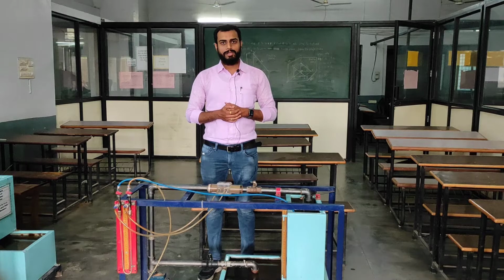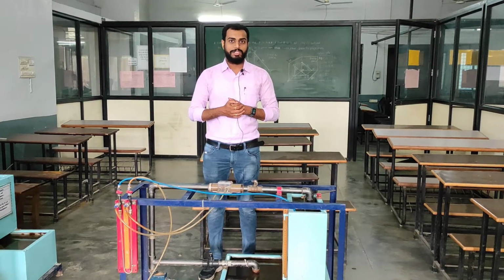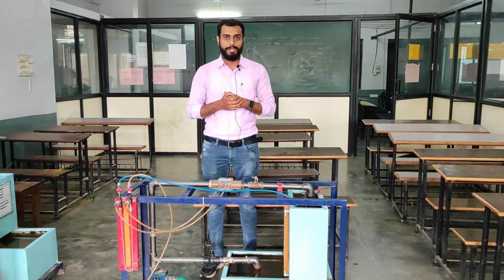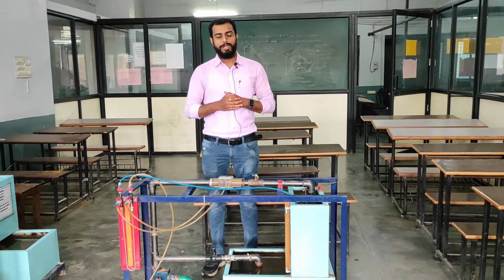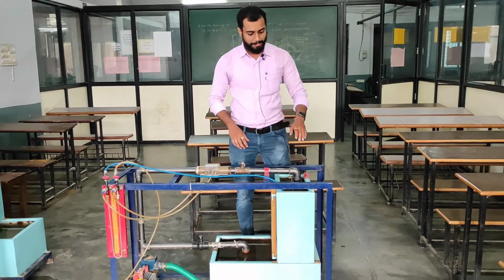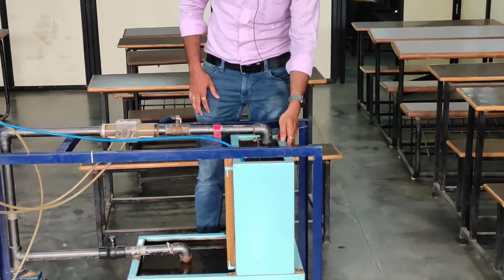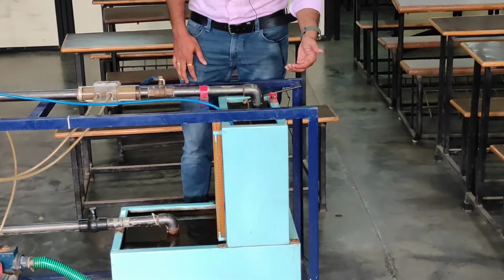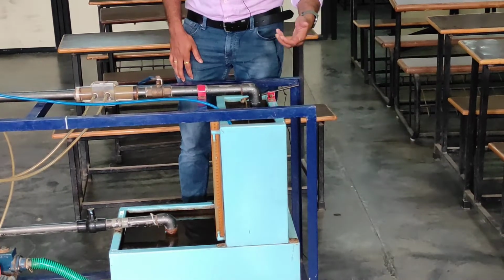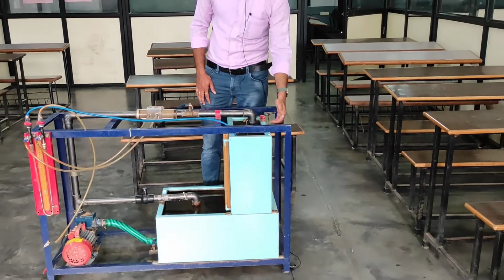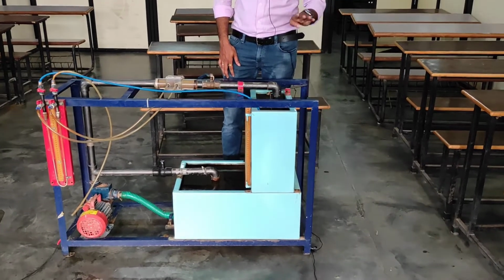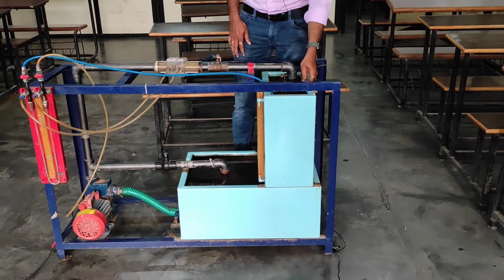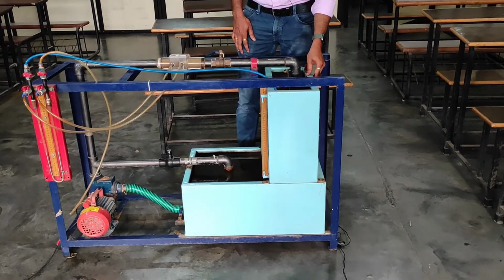Now to find out the CD, that is coefficient of discharge for this Orifice meter, the simple equation is CD is equal to Q actual by Q theoretical. Now first is Q actual. Q actual is discharge actual, so we can measure the actual discharge using this particular discharge tank. Here we have to find out length, width and height for the tank, right? And for the same height the time taken for filling the water, right? So these 3 and 4 readings will be taken, L, B, H and time, for the Q actual. So that will give us Q actual, that is volume divided by time in meter cube per second.